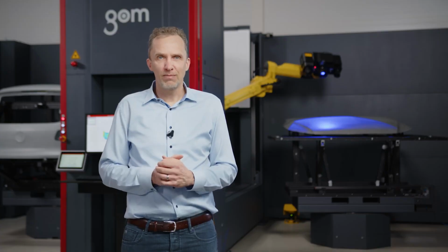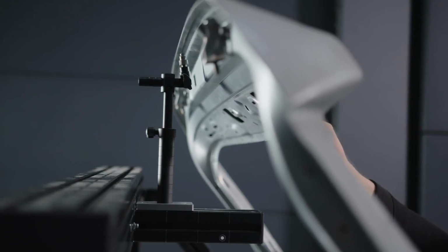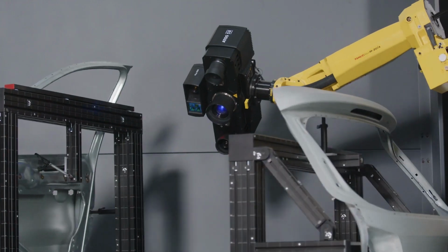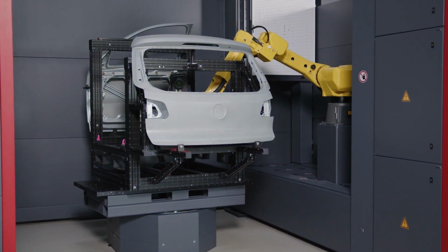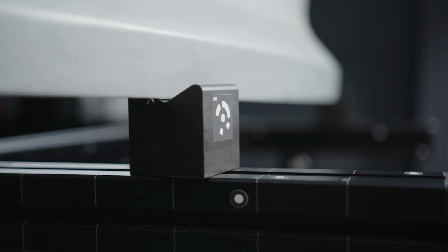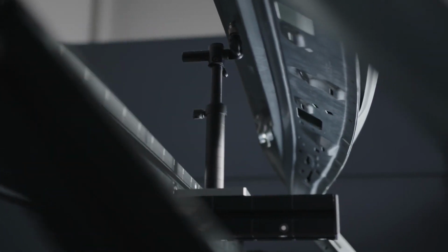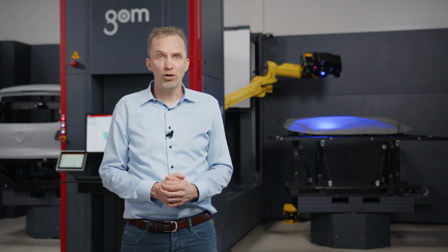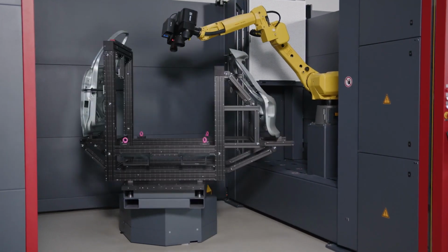We can apply the same strategy to other automotive hang-on parts like trunk lids and doors. Also here we need only one measurement. We do not have to clamp or adjust, and thus we can use very basic, cost-effective and simplified holding fixtures. With virtual clamping for hang-on parts, we can save a lot of time and thus easily save like 20 or 30 minutes per part.